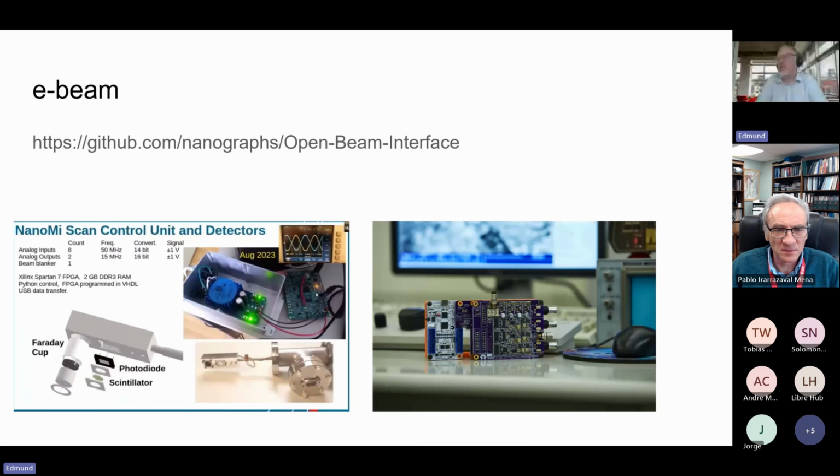This makes old hardware much more usable because it grabs the signal pretty early in the analog chain and digitizes it, and therefore the analog section of the microscope is not used, and this way the images can be of much higher resolution. So that's a way to upgrade old equipment and make use of old and cheap equipment.